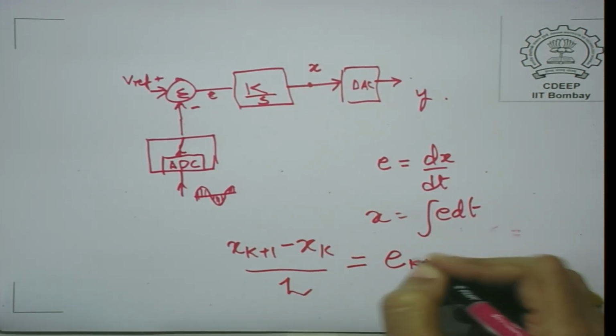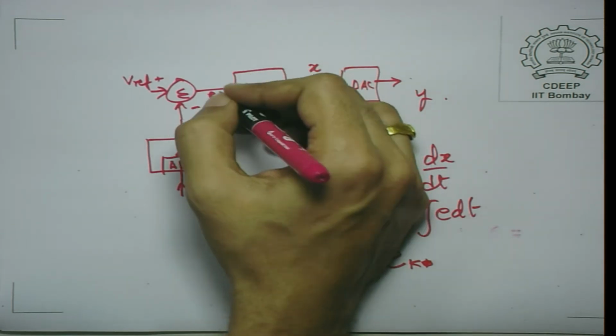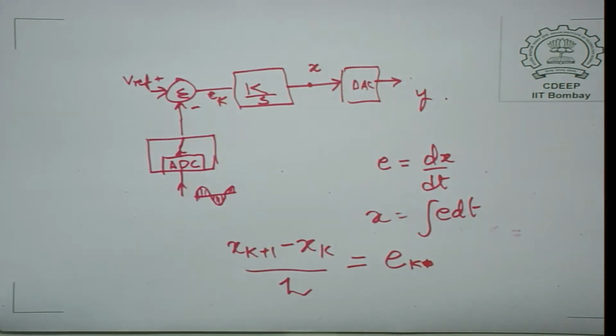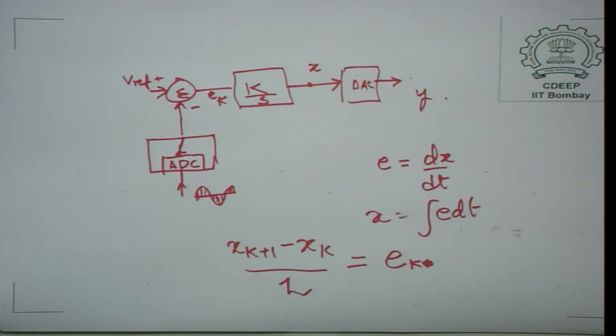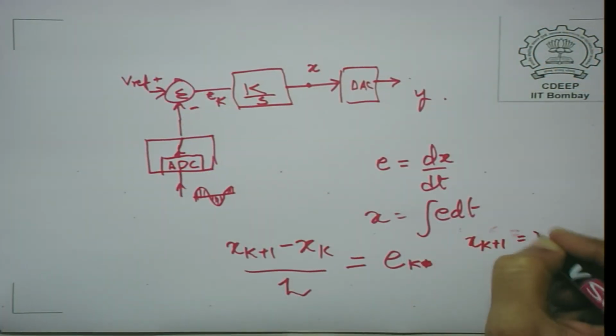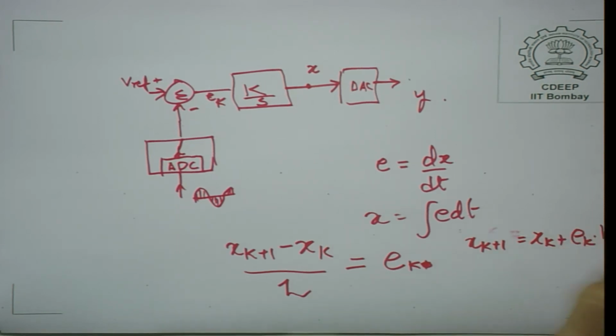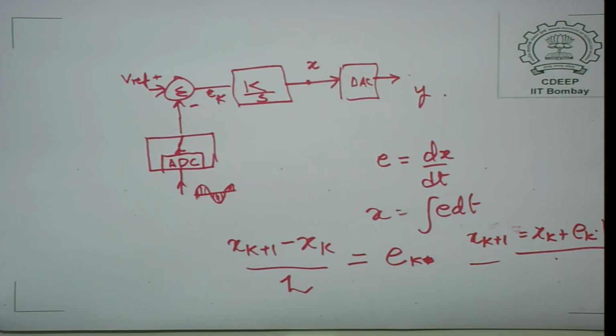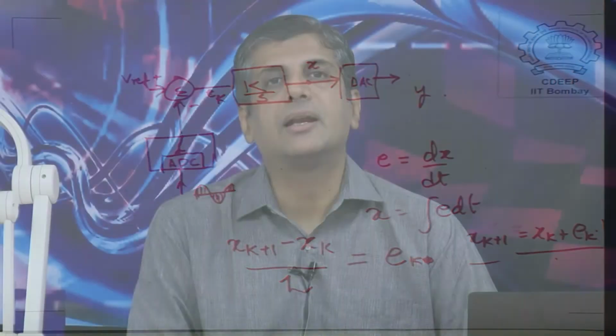So, you get each sample E, this is of course discrete time. Remember, computer does things in discrete time, k represents a sample of the discrete time. If the time difference between the samples is h, then you can implement an approximate integrator by simply applying this algorithm. This is called an Euler algorithm, where you have emulated a continuous time integrator using a digital algorithm. Okay. So, the key steps of course are sampling at a high enough rate, so that you represent the signal appropriately.